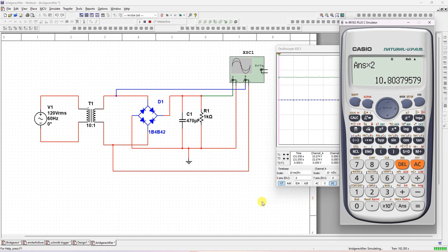That is the case without filter. That is the output without the filter. But with the capacitor filter, now it is coming almost 15.1. For with filter, how to find the DC value, a different formula is there. You take Vm, and from Vm you subtract the ripple voltage peak to peak value divided by 2. So now the DC is actually better than without the capacitor filter.